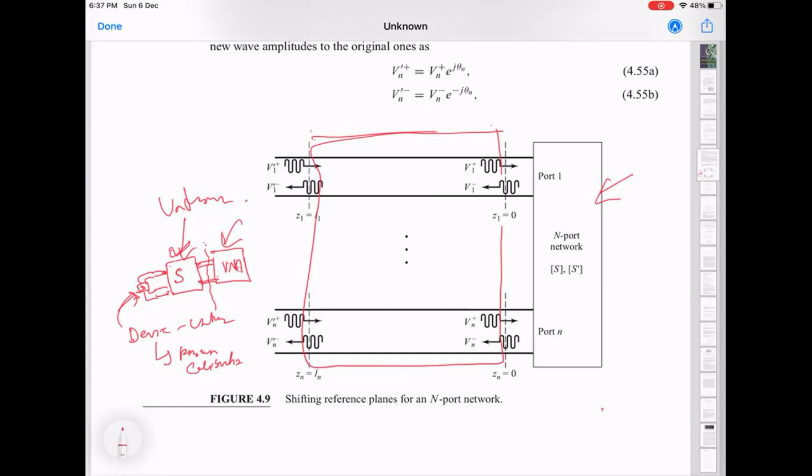So you see, it's sort of the reverse of the process. You now put a known device to figure out the unknown S matrix in the middle, and this procedure is something which the instrument itself allows you to do. It will tell you connect this standard, and then you take a measurement. Then it will say connect a different standard, and it will take another measurement.